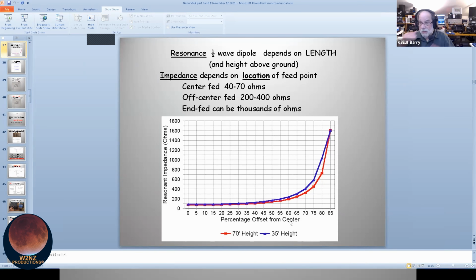Why? Well, because the ground's somewhat of a reflector. The radiation goes down, comes up. The reflected energy hits your antenna. So it's like wham, wham. And sometimes they interfere, and you can get a very low impedance at your feed point. So generally, as you lower antennas, the feed impedance lowers as well, as low as 10 ohms or something. What if I don't feed it in the center? What if I feed it off center, like 1/3, 2/3?